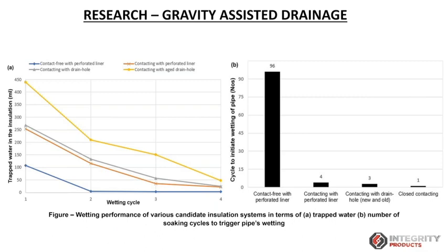Even if the moisture is being trapped in the system, but it's not wetting the pipe, it's not a concern. The concern is the time when the moisture comes in contact with the metallic pipe and it starts a CUI process. So keeping in view the geometrical configuration and the gap and all those things, we did some calculations, because we cannot run the simulation for this one.